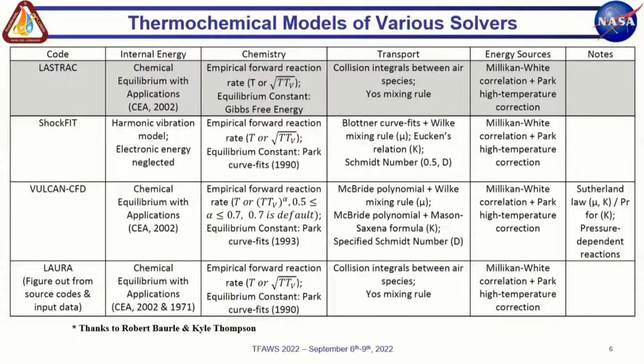The first step, we need to solve the mean flow, to get a steady flow solution. And then for the second step, the stability analysis, we impose a disturbance on the mean flow to check how this disturbance evolves when it propagates downstream.